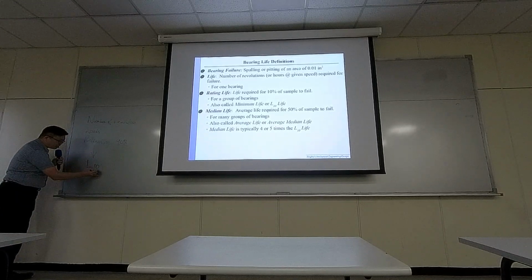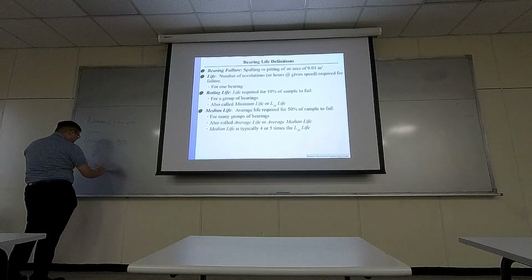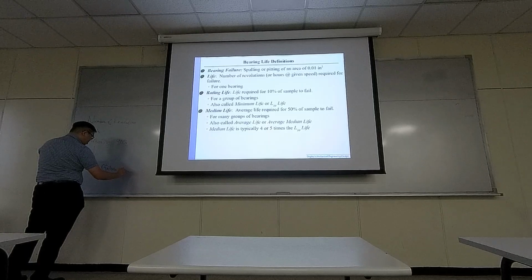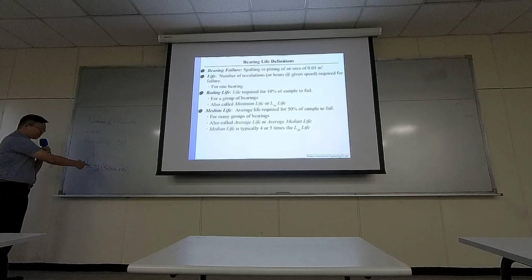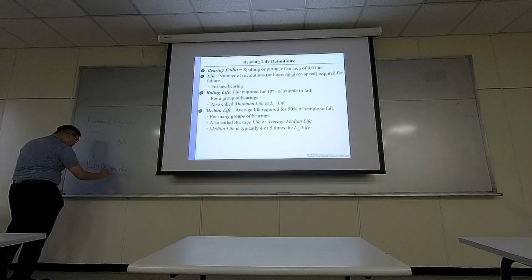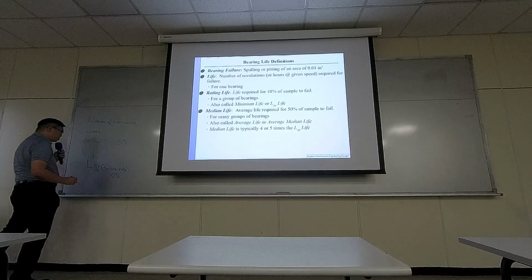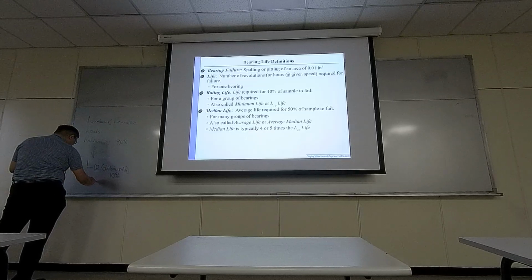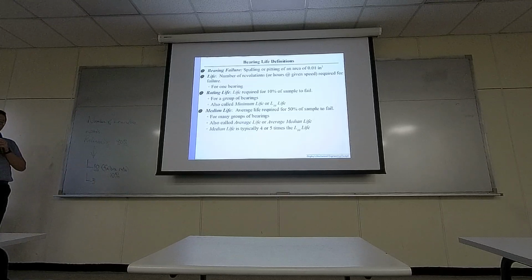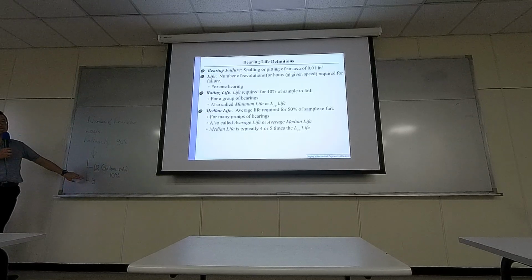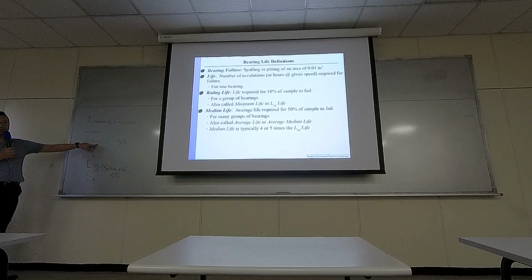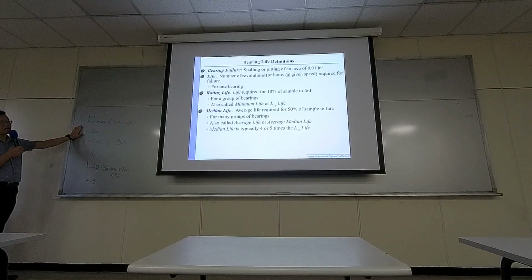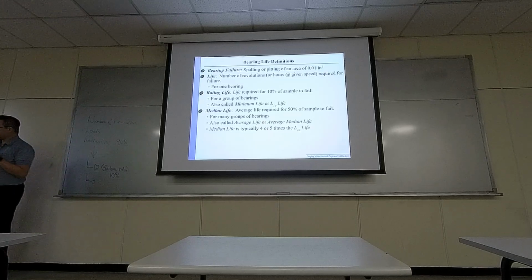The 10 represents failure rate, because 1 minus 90% is 10%. So 10 is actually representing a 10% failure rate. So you can compute life at different values, like L5 or other numbers. L5 will mean you are looking for reliability of 95% after a certain amount of revolutions while it carries a certain amount of loads. Okay?